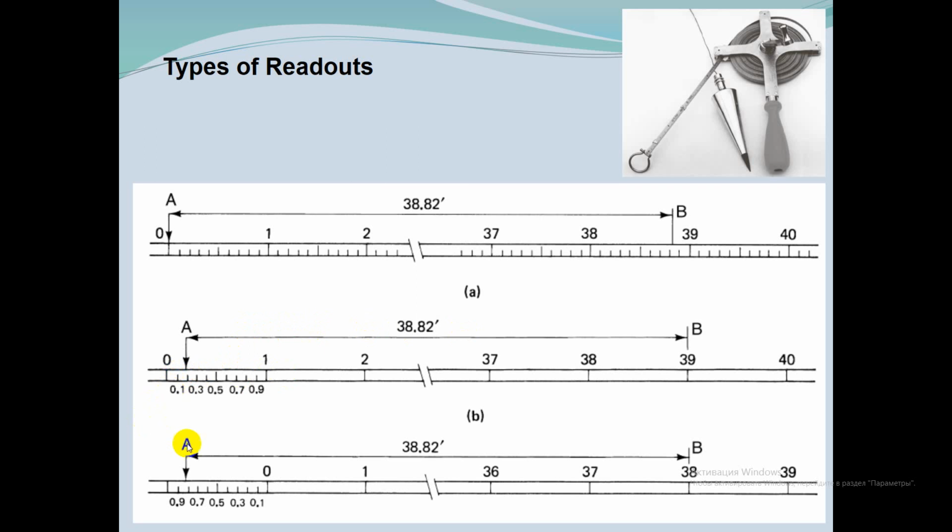The edge tape is also marked throughout in feet with the last foot graduated in hundredths of foot. An additional foot graduated in hundredths is included prior to the zero mark. For metric tape, the last decimeter and the extra before the 0 decimeters are graduated in millimeter.